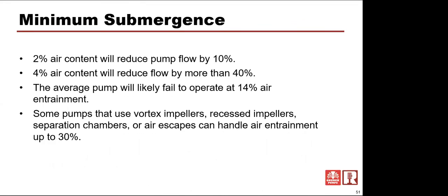Talking about what the effects are, on say an ANSI pump, 2% air content may reduce the pump flow rate by about 10%. 4% may decrease the flow rate by about 40%. Remember that air is very compressible, so it takes up a larger volume in an air state than it would under pressure.